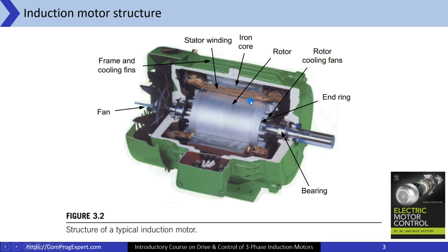So here we have the stator iron core, and this is the stator winding. In this case, we have a copper winding, and in the case of three-phase induction motors, we have a balanced three-phase winding. All phases are identical, just we have a shift between the magnetic axes of the phases. We are going to generate a rotating field, a sinusoidally rotating field, using the stator winding.